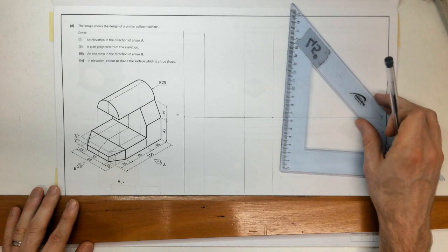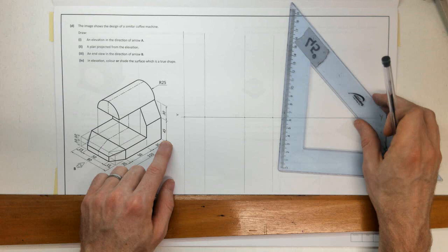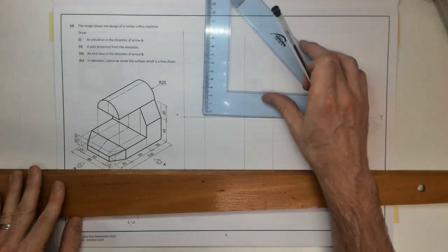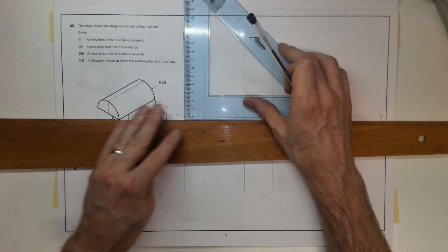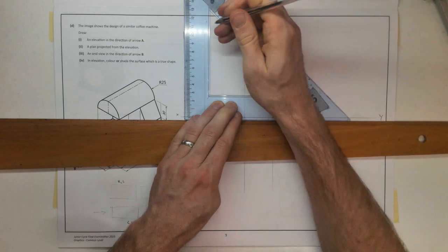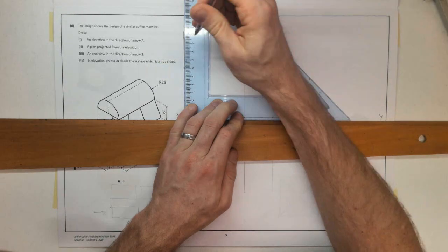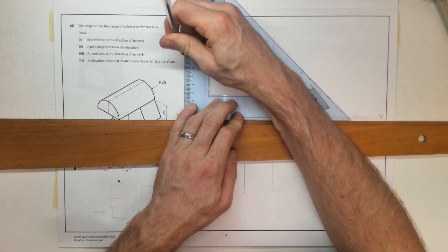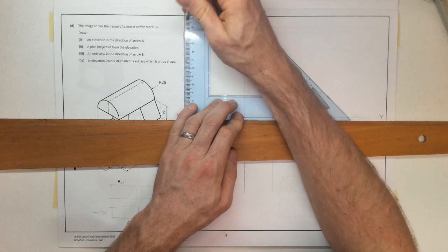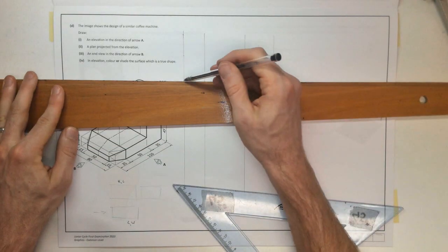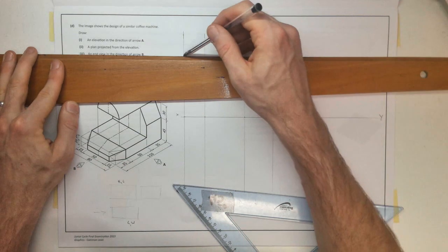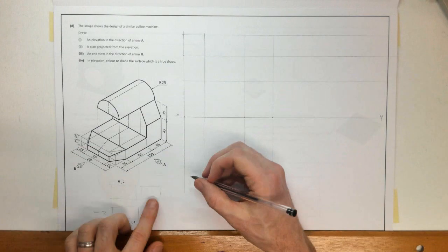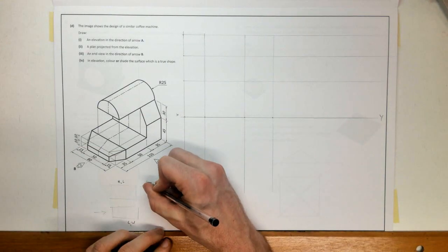My height then, so the overall height we said is 100. We'll just double check that. It's 30, yeah. So I'm going to mark off 45 and 30, that's 75, and 25 above that, so that brings us to 100 now. Okay, and I'll project those sides across, and I'll extend them further than I need because I'll use them for the end elevation as well, because for end elevations we use height and width.